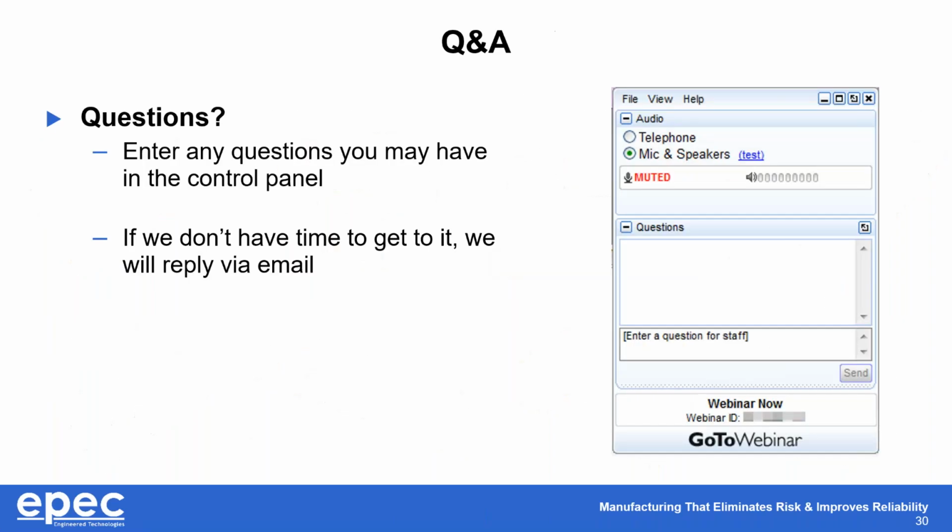I've got one question here. What is the bending lifespan of a dynamic flex? Can I expect it to fail after 10,000, 100,000 bends? That's a little bit of a difficult question, and the reason is IPC, when they consider dynamic flex, they like to use the term infinite. It's not truly infinite, but that's the term they like to use.